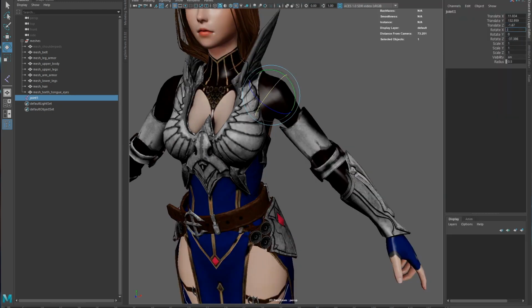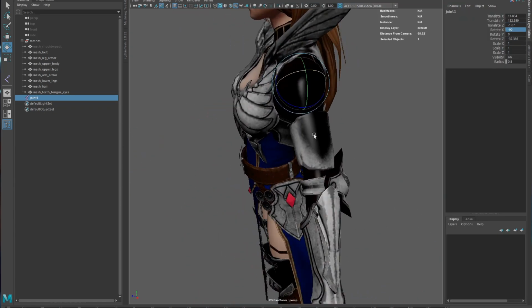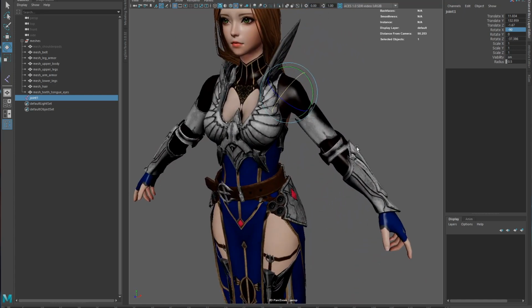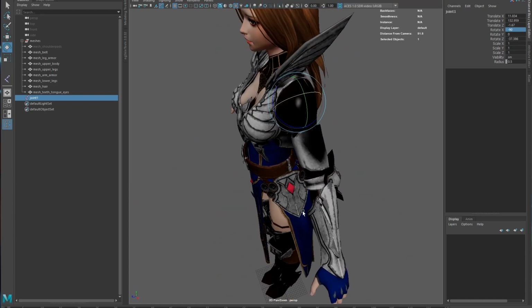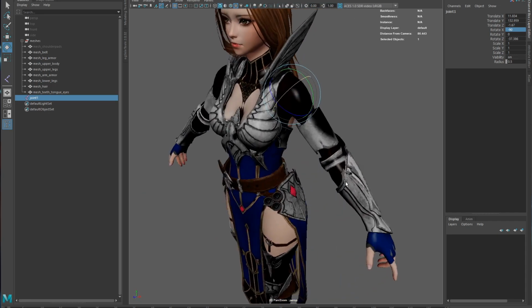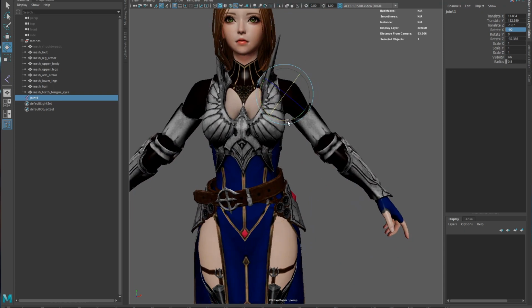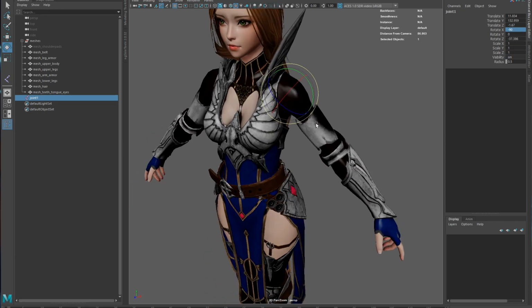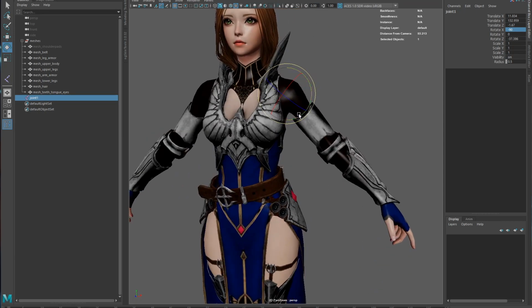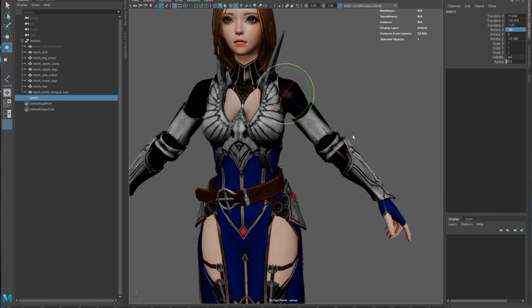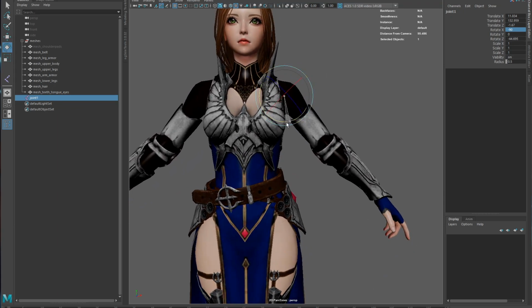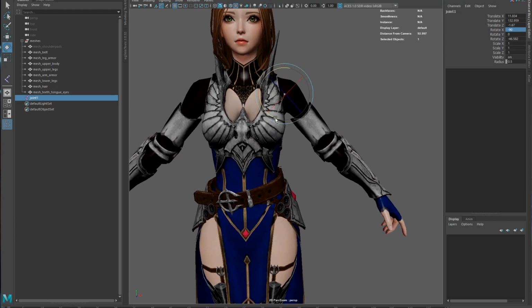So we probably want to do something like this. Let's set that to -90. Because our elbow is going to be a bend axis, it doesn't swing. So being able to go beyond 90 degrees on the elbow is important. And with the Y axis, the swing axis here, normally if you get to this point, your clavicle is going to start kicking in once you go beyond, and that's going to help a lot keep us out of gimbal lock, because the clavicle is going to give us a lot of motion there. So let's tweak that a little bit so it goes down the arm a little bit better.